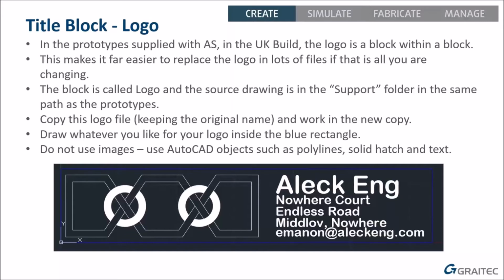I would highly recommend you replace any images with AutoCAD objects. So you can insert the image, trace over it with polylines, use solid hatches to fill in areas, then detach the logo. Don't just delete it, you have to go into XREFs and detach it, because it will still be linking and it will come up with an error every time you open a drawing. I can't find the logo, I can't find the logo. So make sure you use the detach option inside the XREF palette.